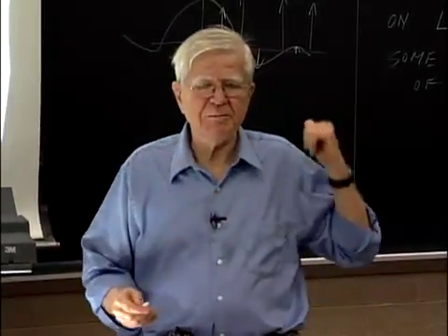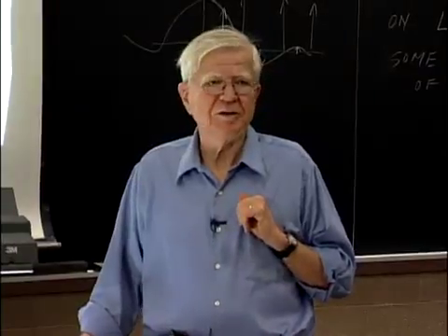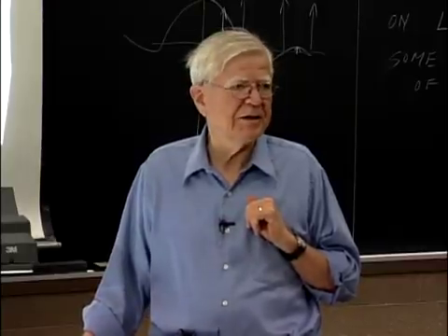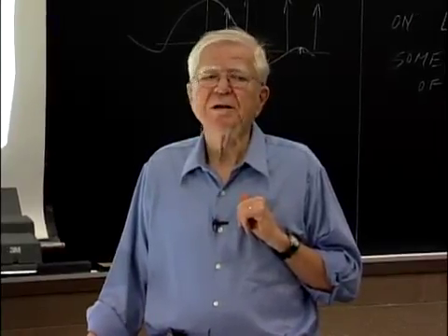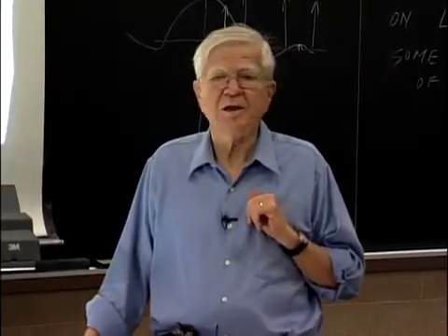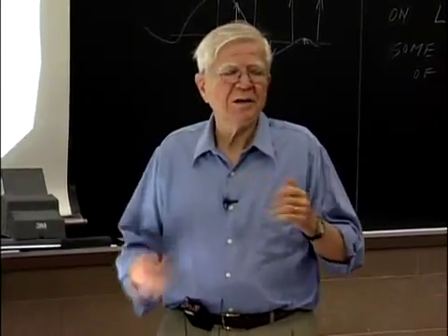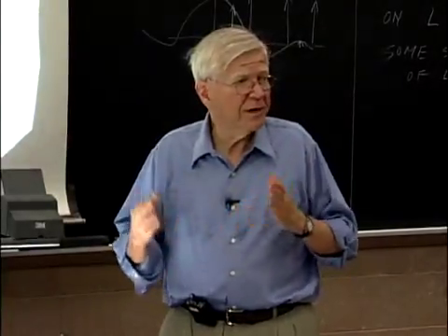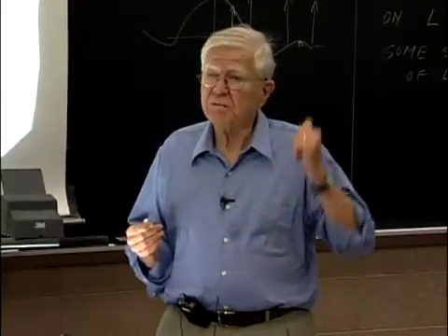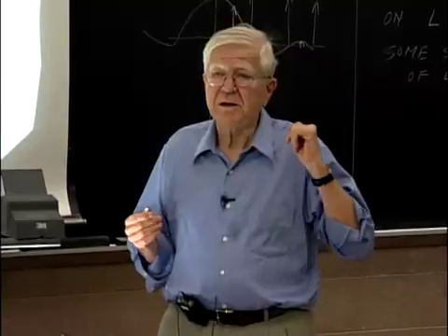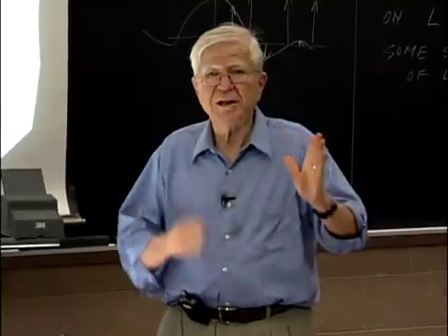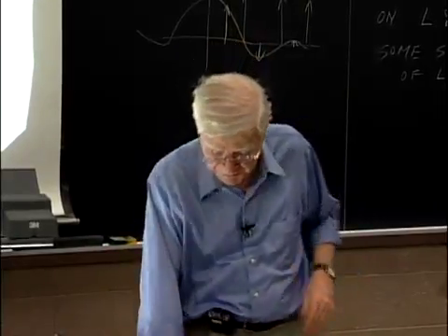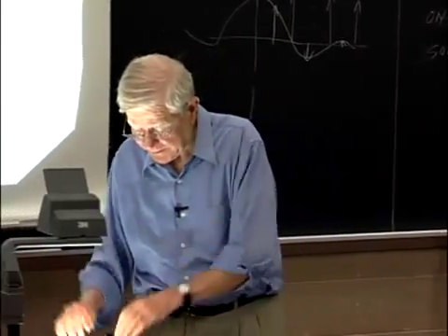the sample time on this discrete model is about 0.8 of a microsecond. If you think of how far light can travel in 0.8 of a microsecond, it's about the same as the multipath spreads you would find outdoors when you're in a relatively rural area. If you're in a city area, the multipath spreads are going to be even smaller. So if you want a rake receiver to work well, you should really have a rake receiver which is trying to zero in on the actual physical response times, which is what this system does. So they did it right and I did it wrong, okay?